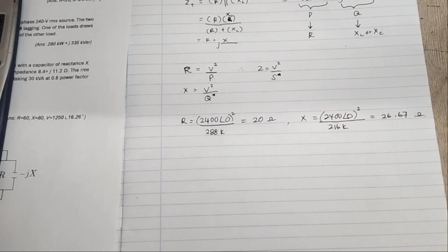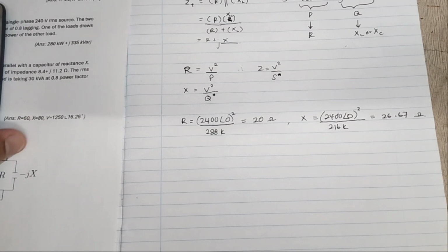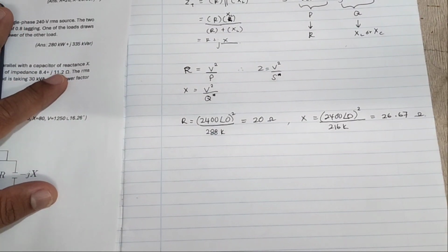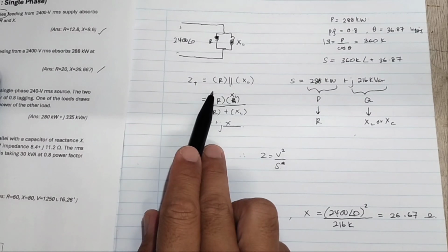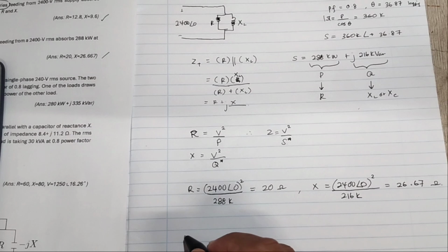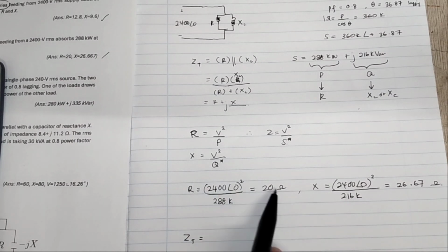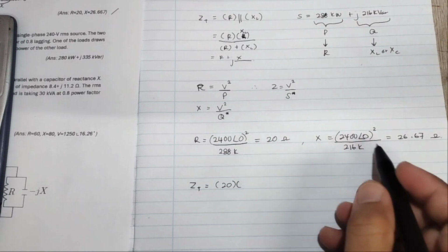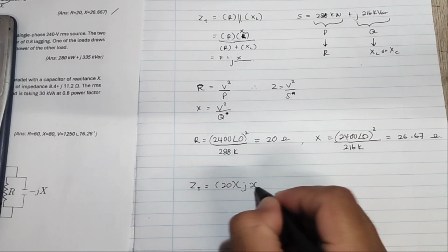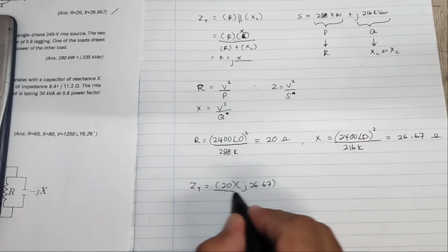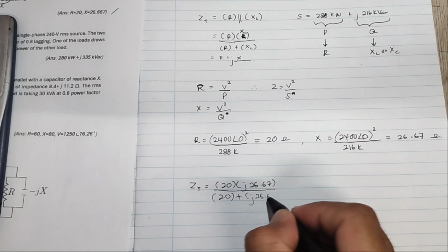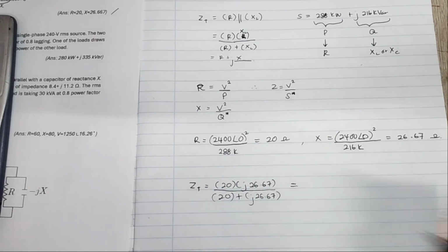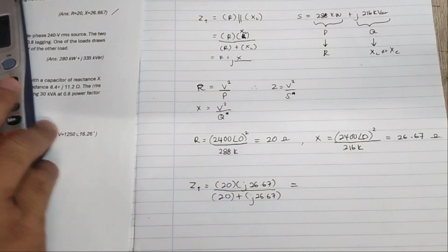So we try to derive. Is it sama tak dengan Z total yang question number 1? Okay, right? So tadi Z total sini adalah, okay, R parallel dengan XL. So Z total is R 20, okay, parallel, maksud dia yang atas darab J 7. This one is X divided by 20, bawah tambah kan, J 7. Macam tu. Okay, right. So tekan calculator dapat berapa?